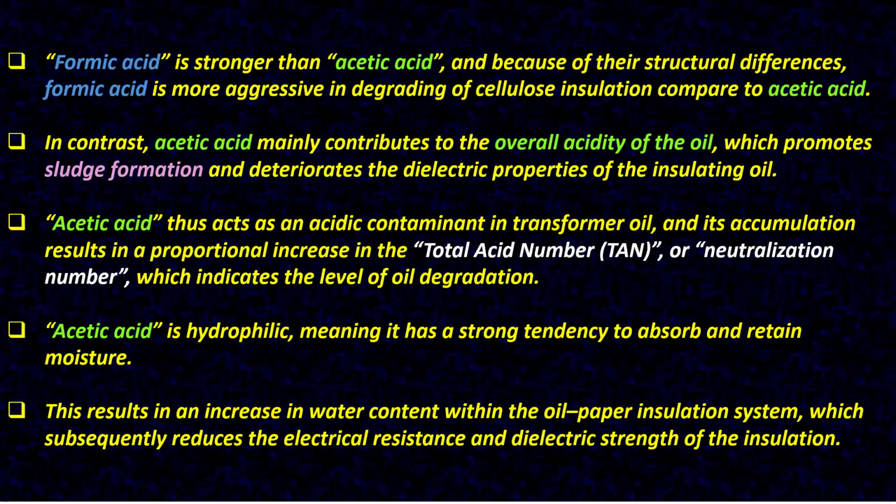This results in an increase in water content within the oil paper insulation system, which subsequently reduces the electrical resistance and dielectric strength of the insulation.